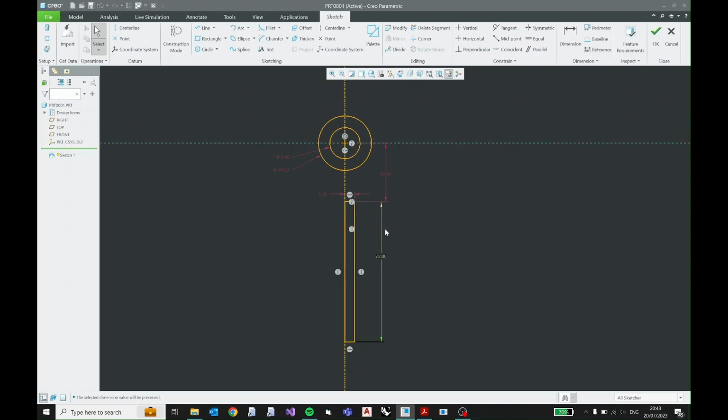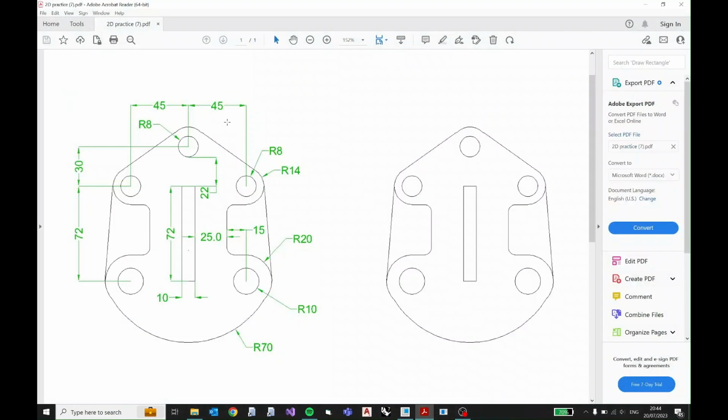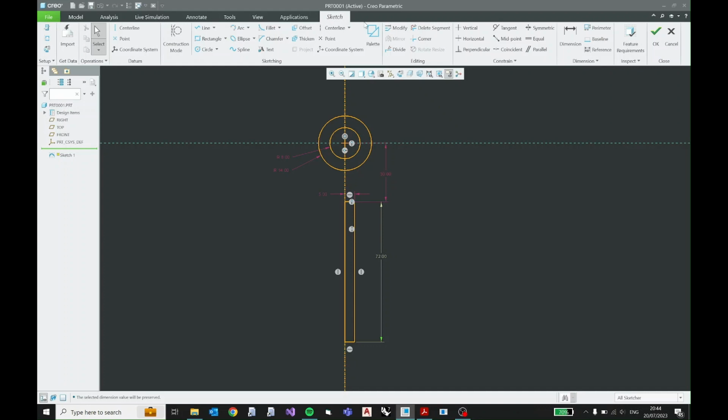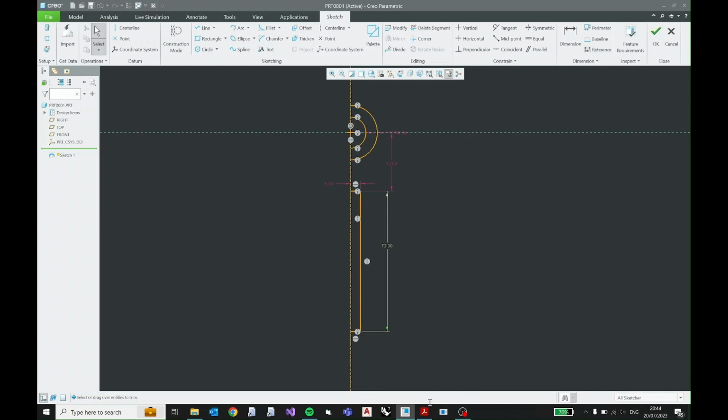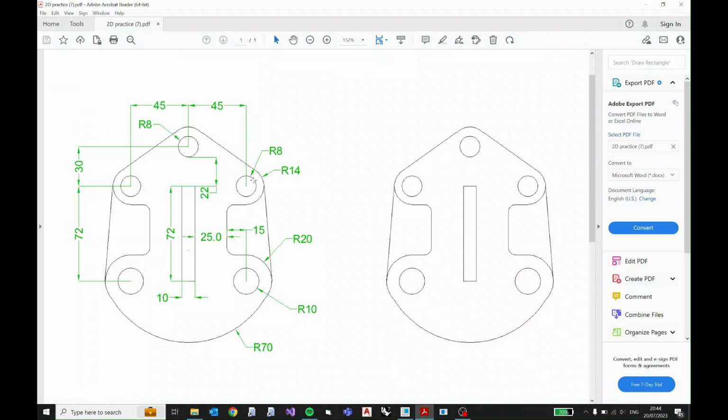Now, as you can see, we've got a whole circle and a side of a rectangle existing over here. We don't need the whole circle or the whole arc because obviously we're going to be mirroring it in the end. So I'm going to get rid of this side. I'm going to go over here, select delete segment, and then click and drag the mouse button over the parts that I don't need. So it's going to delete it, and then also this line as well. Press escape. Perfect.